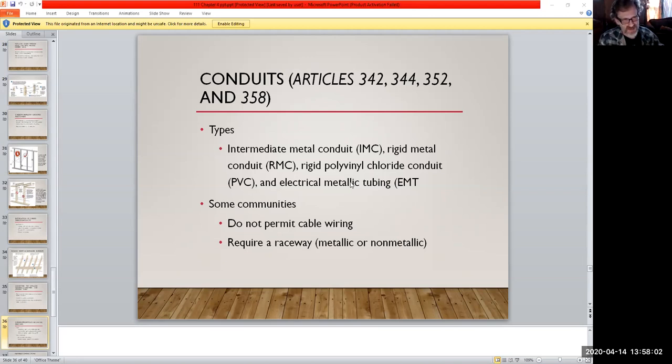One, it'll be a royal pain in the butt trying to pull wire through. And two, if you have heat buildup and it's crammed, the copper will expand and it'll literally degrade your insulation. Ugly's book, and like I say, the NEC definitely has some real good tables and charts. So if you have half-inch conduit and you're dealing with number 14 wire, how many number 14 conductors can you get through a half-inch conduit? And it tells you exactly.